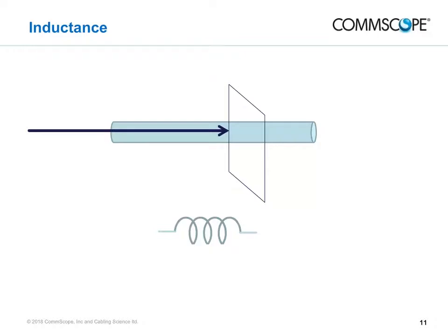The effect of inductance is increased when the conductor is wound into the shape of a coil or solenoid, by the square of the number of turns in the coil. This is probably the reason that in electrical circuit diagrams the symbol for an inductor is a coil. Inductance is measured in units called henries, which represents volts per ampere per second. Smaller values typically found in practical inductors are 1/1000th of a henry, called a millihenry, and 1/1,000,000th of a henry, called a microhenry.